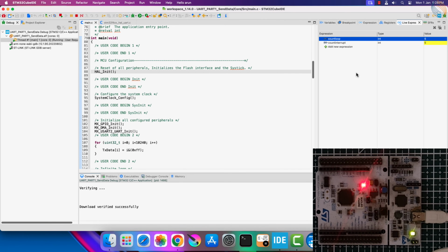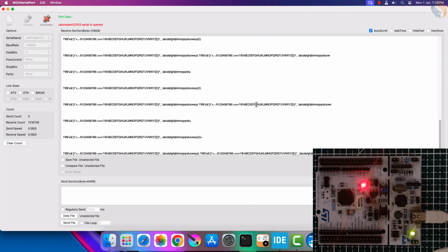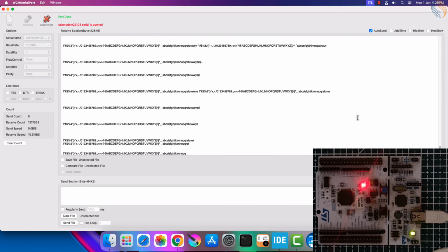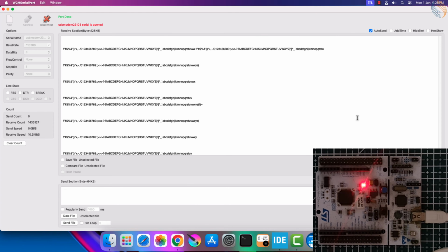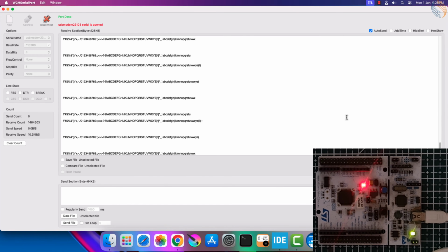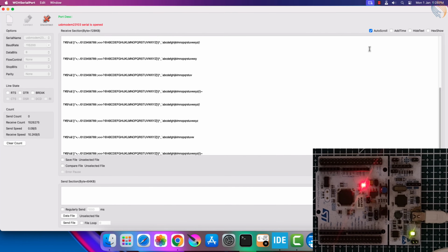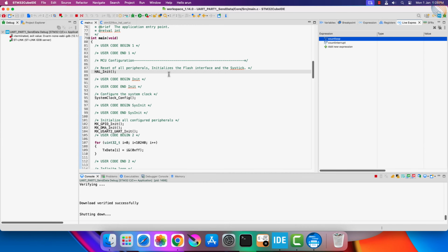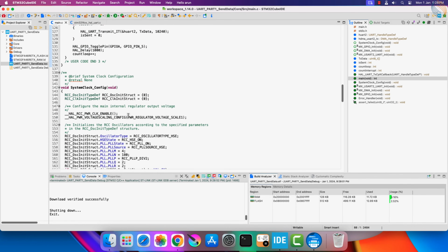Now you see both the counters are incrementing at the same rate. The LED now blinks every 1 second. The data transfer is still continuous, and it does not take the 1 second delay into consideration. This is because the data is transferred in the background, and by the time the CPU waits for the whole delay to finish, the data is transferred. Then the loop calls for the transfer again.